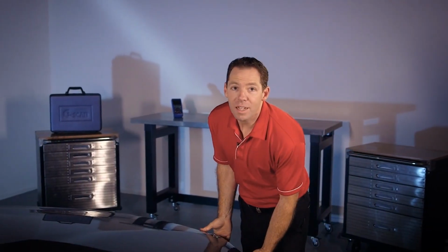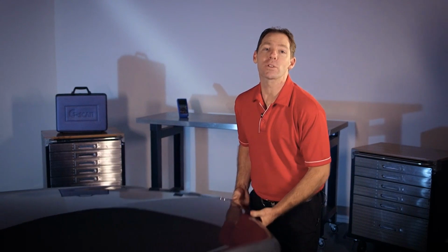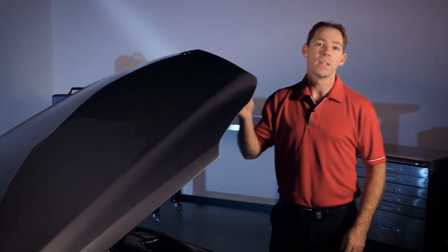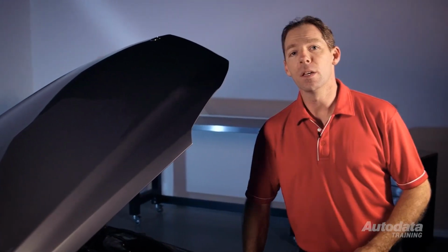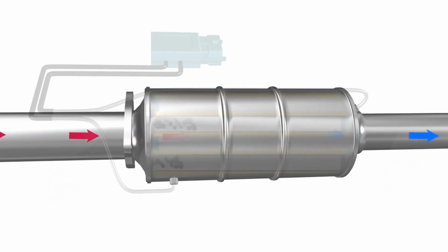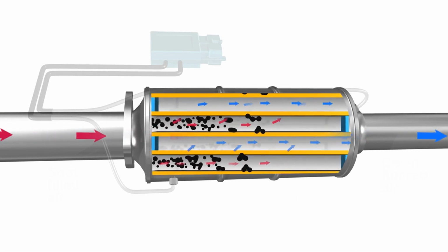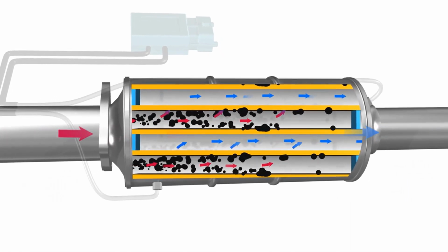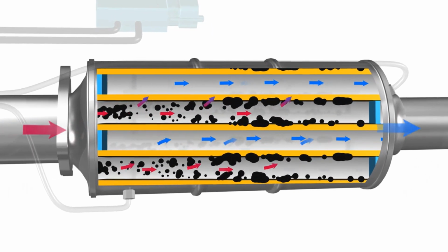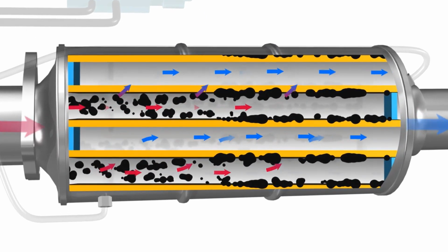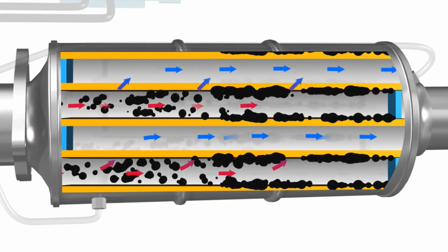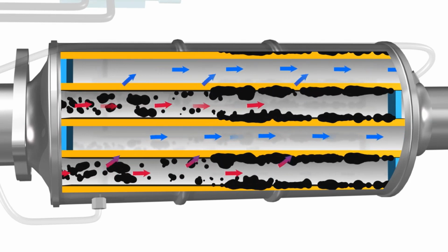Diesel particulates are typically soot particles with adherent hydrocarbons, sulfate and other condensed compounds. Soot particles are known as PM, or particulate matter. The collected particulate matter in a diesel particulate filter, if not removed, can create an obstruction to exhaust gas flow. The particulates are removed by a regeneration process which incinerates the particles.